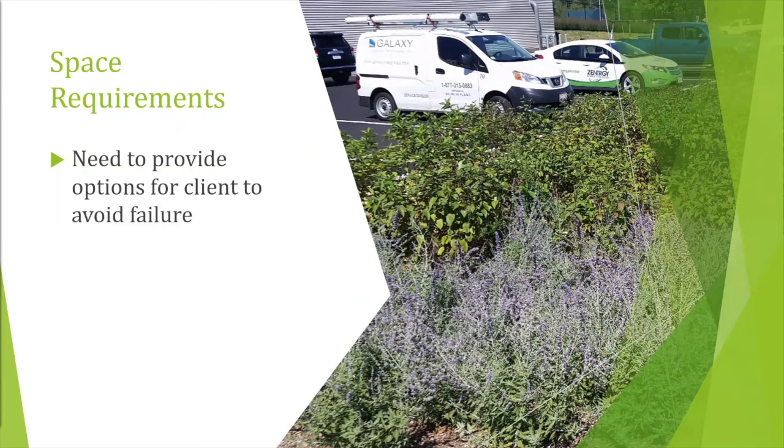Space requirements, I talked about this. Again, this is where I think the cost benefit analysis is always key for a client. This is a bioswale that we designed for a commercial space down in Baltimore. In a commercial space, they want the parking. They don't want anyone to not shop at their store because there's not enough parking. But we really needed a wide swath for the bioswale so that we could properly handle all the flow. So we showed them the bioswale would reduce the need for an underground water quality system. That was a state requirement.